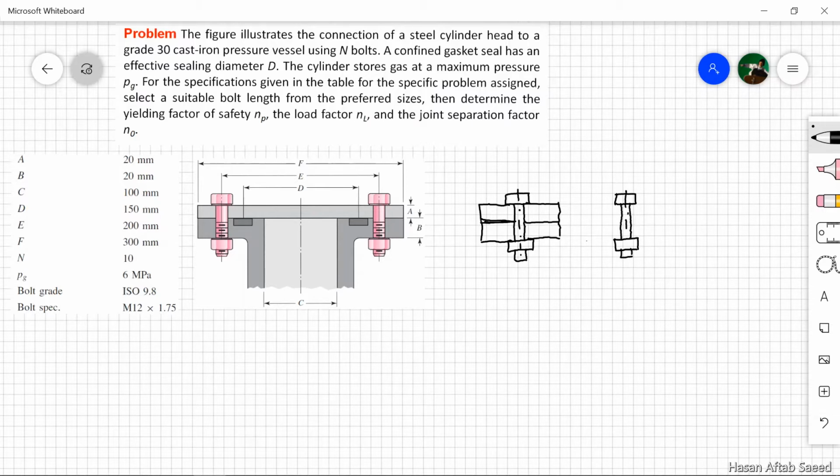So this is your bolt with a nut, and part of it will have threads like this. So let's talk about the different lengths of the bolt. This is the total length L, and we are supposed to find this one, and the length of the threaded part inside the grip, that is LT. Please brush up on the basics. This is one of my lectures on these things.